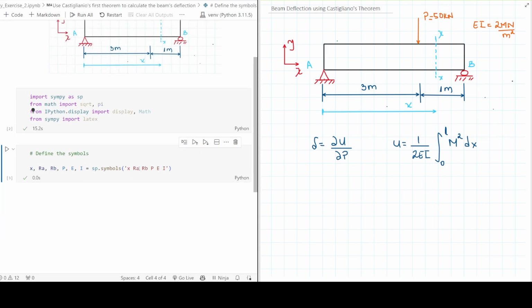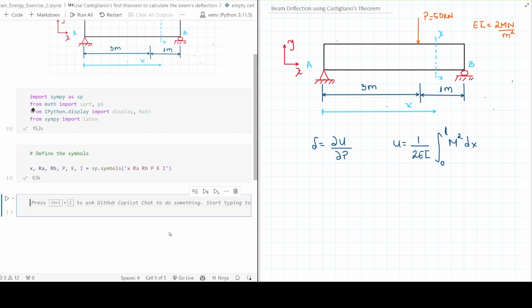And then, again, I need to formulate my shear force equations. Then I need to formulate, using the shear force equations, the bending moment equations. And that's what we're going to do. But first, we need to find out what are the reactions that I don't know, reactions at A and reactions at B. So let me write here then, reaction forces.